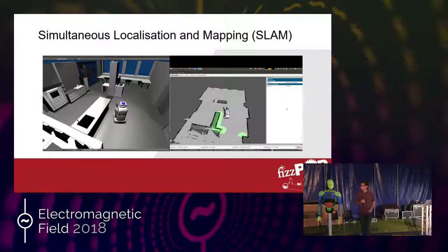I'm using something other than a Kinect, an Asus Xtion, because it has a USB connector, but the robot was originally designed to use a Kinect. Either of them produces 3D scenery in a point cloud representation. So it basically tells ROS whatever is in front of it in 3D.